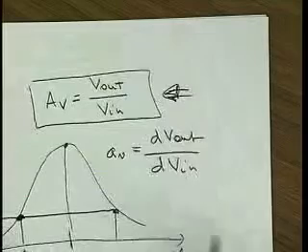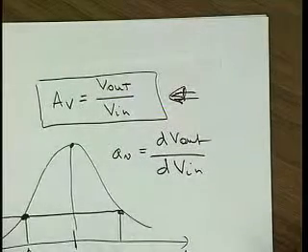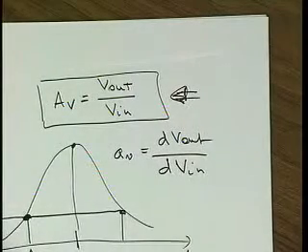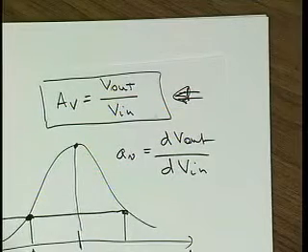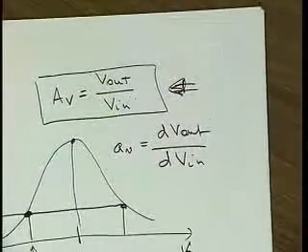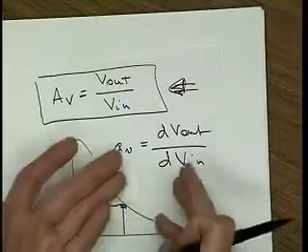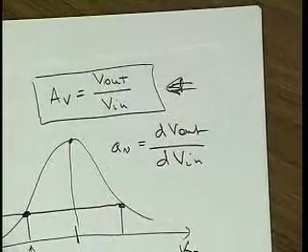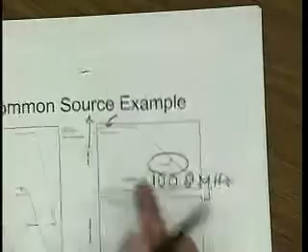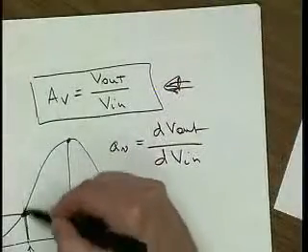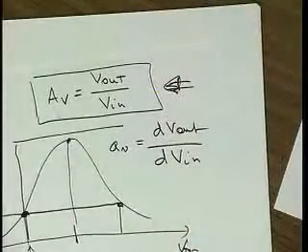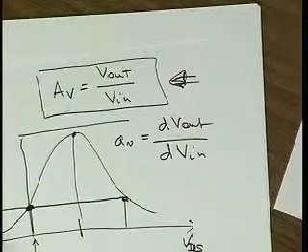And of course, if this lambda story applies, where our output is totally independent of VDS, then these things happen to be equal, and then using this all the time is just fine. And even using this point is just fine, because this lambda story says that we should be getting something like this for gain. But we don't.